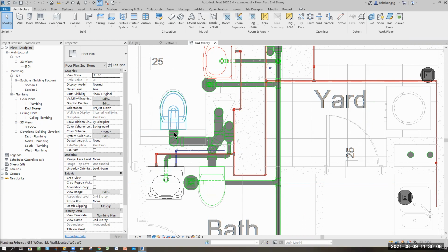It's not from the back, it's from the base. So in other words, try to look for a WC that connects from the base, bottom down. You can link this directly to the piping. No need to go one round like this. It's a bit ridiculous. So in Singapore, we don't use this type. That's why this space given is not for this pipe. It's for your water pipe.